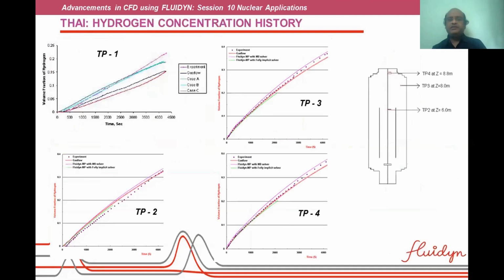And the values of various things like temperature, hydrogen concentration at different points are compared with the experiments. And before finalizing the suitable models to analyze actual problems, various parameters and models like turbulence models are tested, and most suitable models are selected based on this experiment. Then they are used in the actual situations.